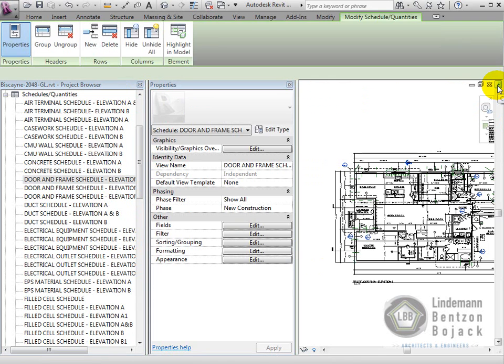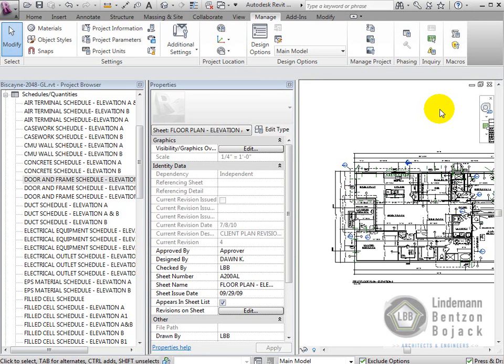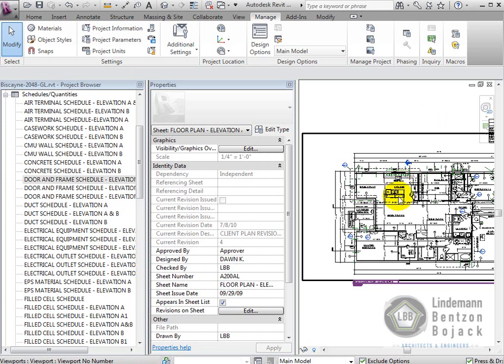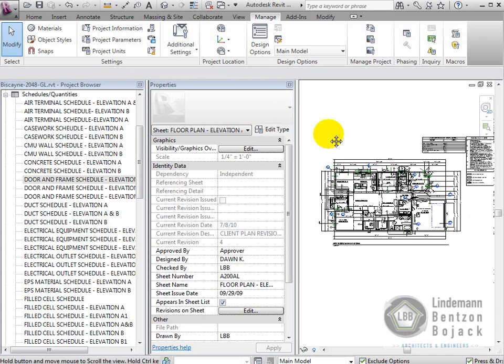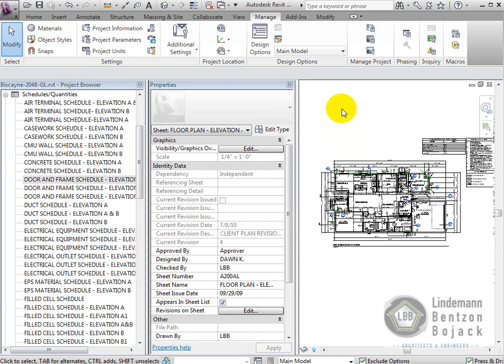So once you coordinate your views, go through your sheets, make sure they're correct, align all your callouts and sections like they are on the right, and then toggle all of your schedules to include linked files, you will have a left-hand model that is set up. Now, when you have to make a lot that's left-handed, keep in mind you're going to manipulate it from your right-hand file. And when we go over creating lot-specific plans, we'll talk about that.